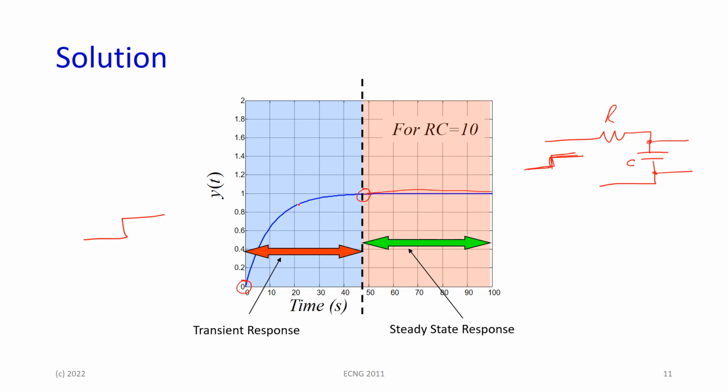So after the step, notice that it doesn't go up and up and up and then come down, and we're going to see things that will do that kind of behavior. And eventually it's settling down to a steady state value, which is equal to the input voltage, which is 1 volt in this case. All right? So by testing the system with a step already, we could get some idea of the behavior of it, and we can verify that the system is at least not behaving unexpectedly.